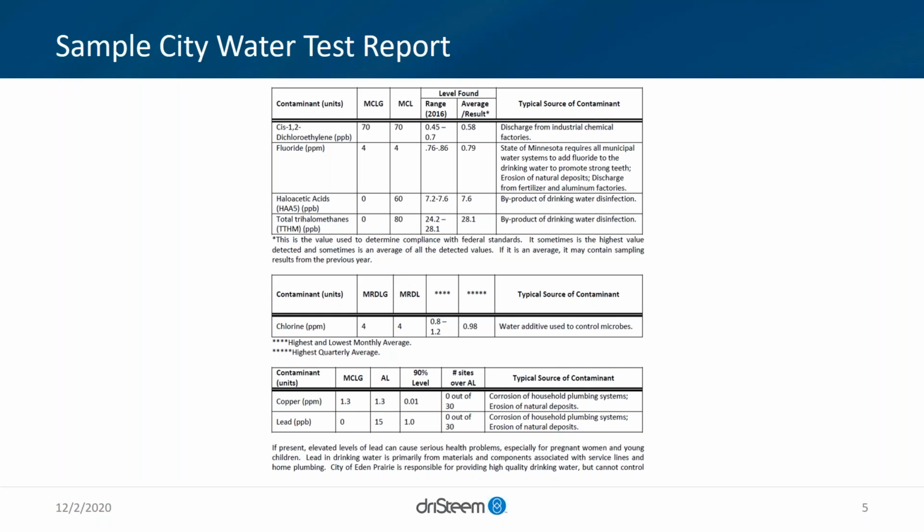But there's other things like chlorides, if any of the equipment has stainless componentry, the overall pH for general corrosion's sake, and the total dissolved solids. All these things are very important, especially when the end user needs to get to the reverse osmosis type quality. And I'm going to go over some terminology in the next slide, actually 2 slides, and we'll talk about what permeate means, what that term means.